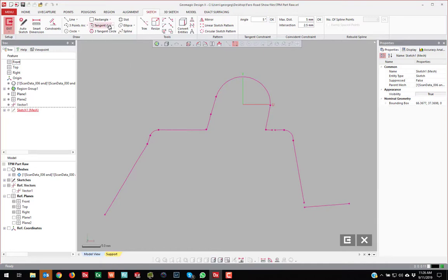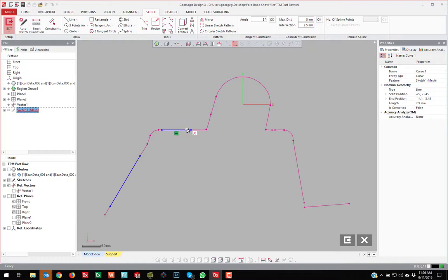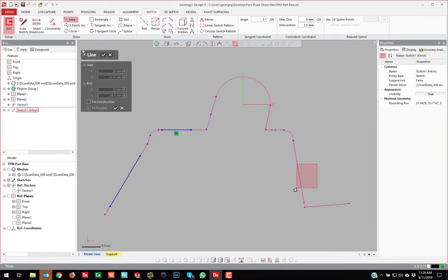So you see this pink line here. I have the ability to window in and best fit data there. I can draw a line and snap it to that data. And if I exaggerate the best fit, if I window in a little bit of data from there and there, it's actually best fitting a line between that selected area.